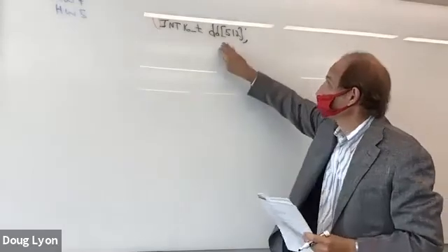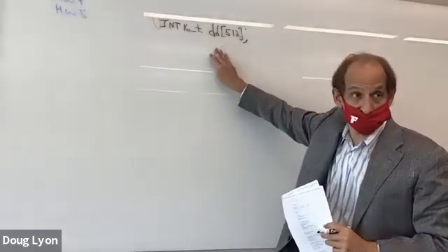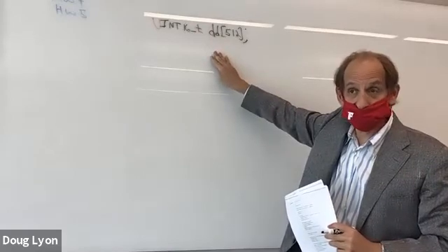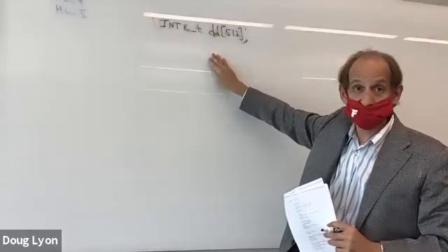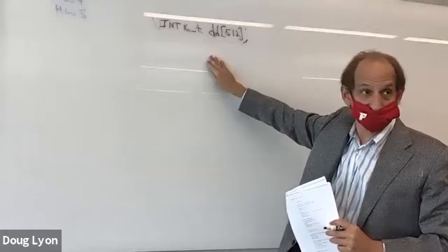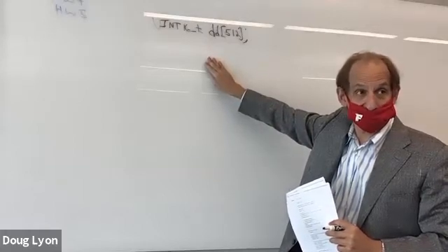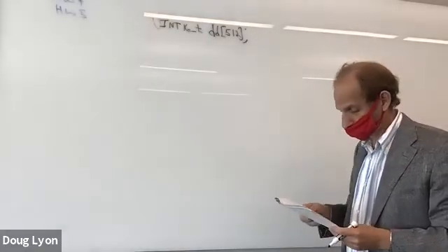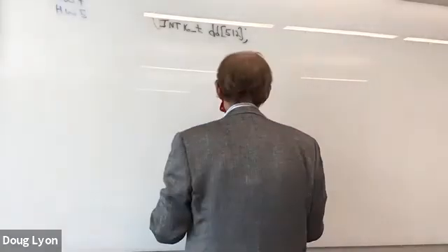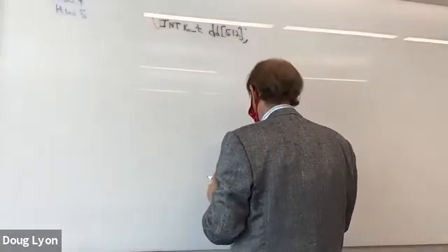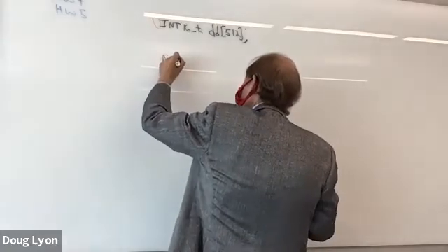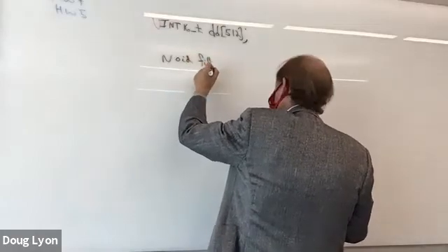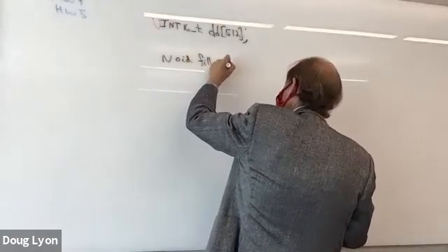What this does is different from what you might be used to in Java. What this does is it allocates 512 16-bit quantities, which is going to take you 1,024 bytes out of your RAM. And that's actually important because you don't really have that much RAM. And now we're going to pre-compute the sine wave. And we'll fill the sine wave with a method called fill sine wave.